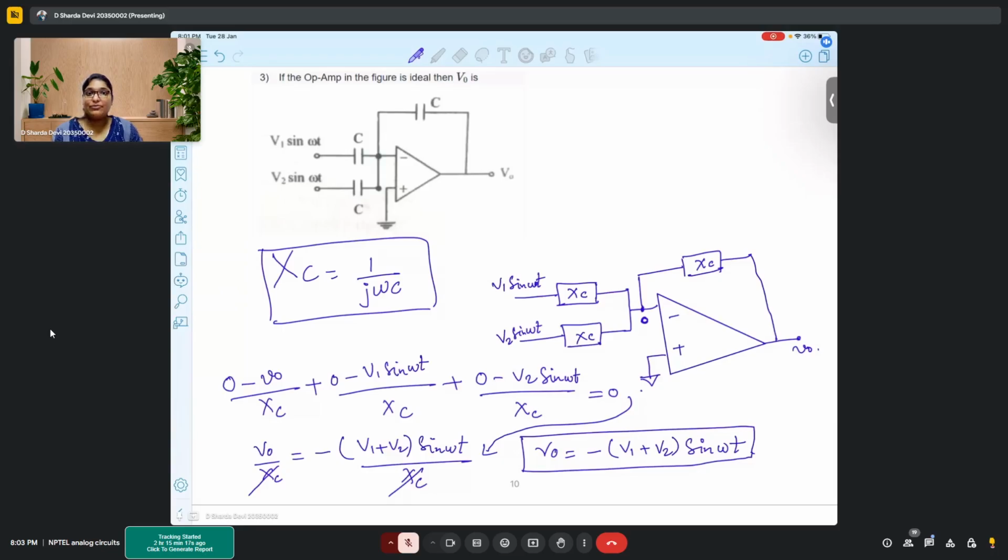When I say negative feedback, but in the same diagram, if I switch my positive and negative, that feedback is not negative feedback anymore. That becomes a positive feedback. So my circuit is a completely new circuit. It will not be an amplifier anymore. Yes, ma'am. So its functionality is different, everything is different. So physics should not change. Pictorially, you can draw it like that. You can just bring down that feedback path downwards. It's fine. Okay, ma'am. Thank you.